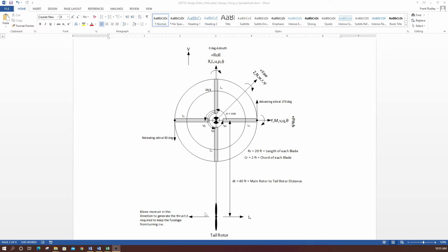We're also talking about the tail rotor. The tail rotor is used for anti-torque, and it generates a thrust. So we'll talk about anti-torque a little bit. What's going to happen since the drive system is in the fuselage? When this rotor turns counterclockwise, it's going to want to make the fuselage turn clockwise, to the right. So we have this tail rotor. You need it, which is a waste of power, but this is the most common helicopter out there.